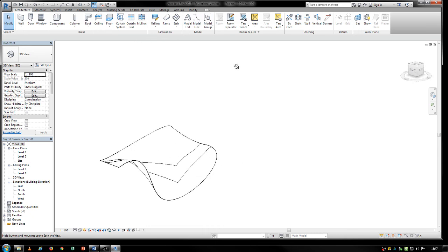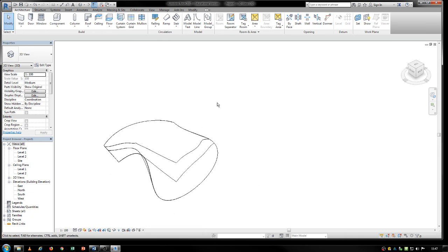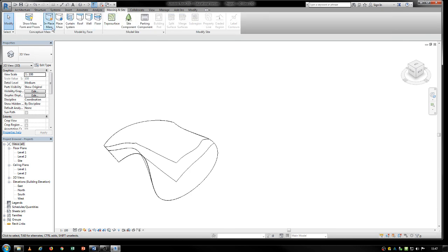As you see, we did this curvature inside. You can do booleans and reductions and additions and draw some things on the wall. So go in and play with the massing a little bit. In the next module, when we're talking about Dynamo and some design elements inside of it, I'm going to show a little bit more examples of this and some adaptive components, how you can define this as a roof structure, and then you can make grids or a unique grid system that would read off of a component and just adapt that to your form.